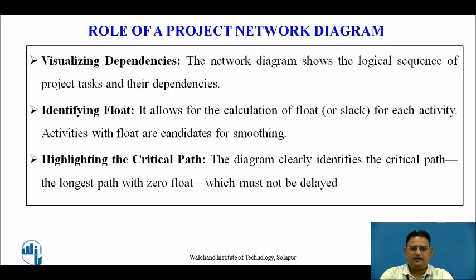This will declare the critical activities and the non-critical activities in the overall project. Once we know the critical and non-critical activities, with the help of the non-critical activities, we can utilize the resource smoothing technique. We can optimally smoothen the resource with all the activities in the project.